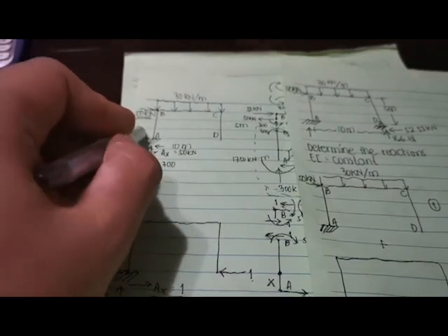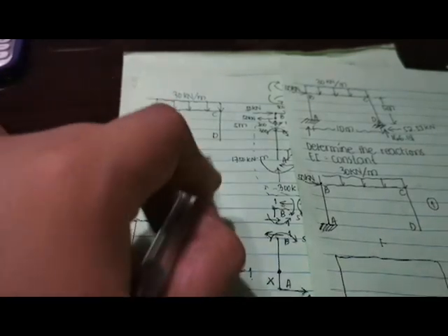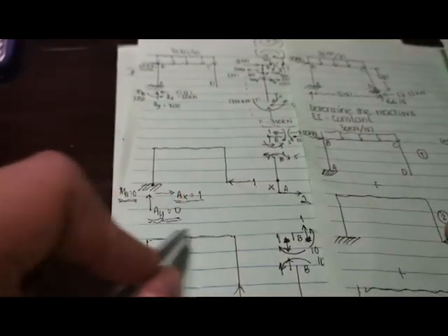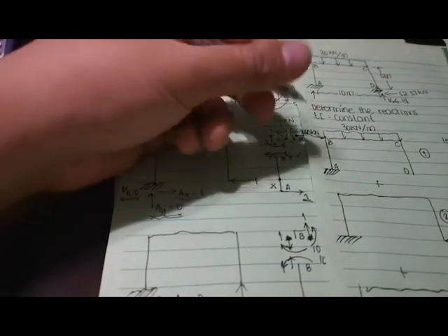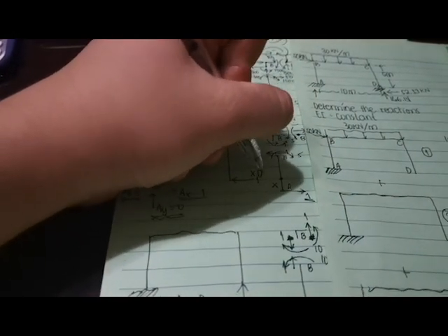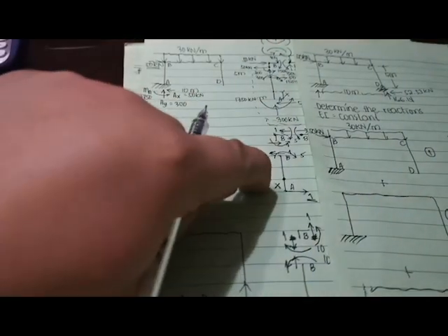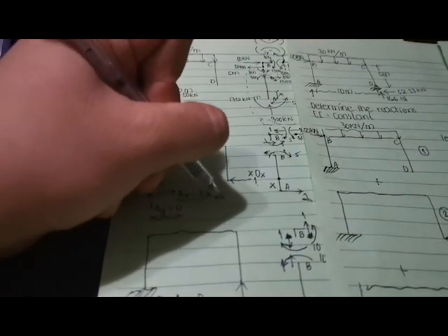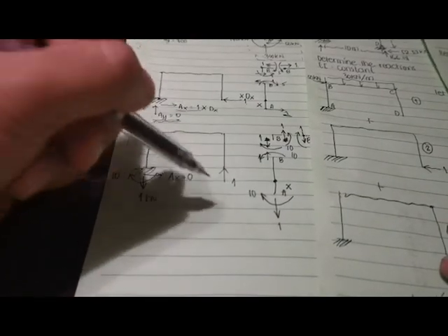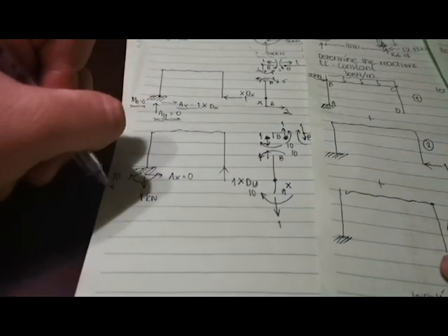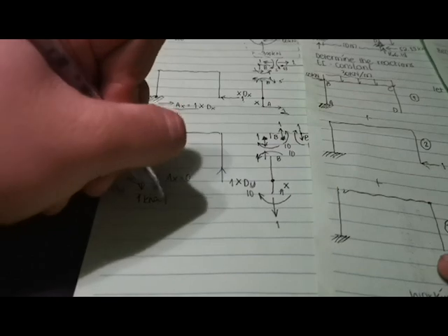you have your primary frame subjected to the original loads. And then we're just going to add all the reactions due to the solved reactions. On the horizontal unit load, since the direction we assumed is correct, we're just going to multiply this by d sub x, the d sub x that we solved. Now we're going to multiply everything here by d sub x. Next, on the vertical unit load, we're going to multiply everything by d sub y. So all our values we're going to multiply by d sub y.